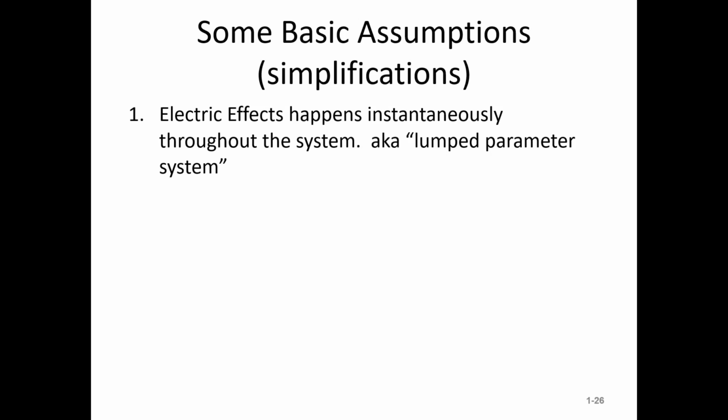Figure out the time. Take say a 1 gigahertz signal. Invert that. That's the time that it takes. Figure the speed of light. Okay. Figure how long that signal could travel before it's out of phase by a significant amount, and it's not far. Okay, so you're starting to reach, with chip clock speeds, the physical fundamental limits of how fast a clock can be. So that lumped parameter assumption is no longer a good assumption.